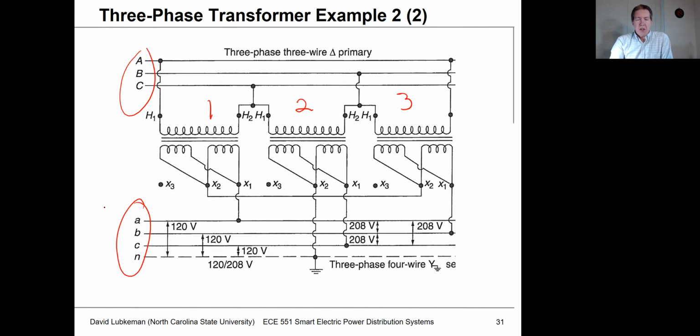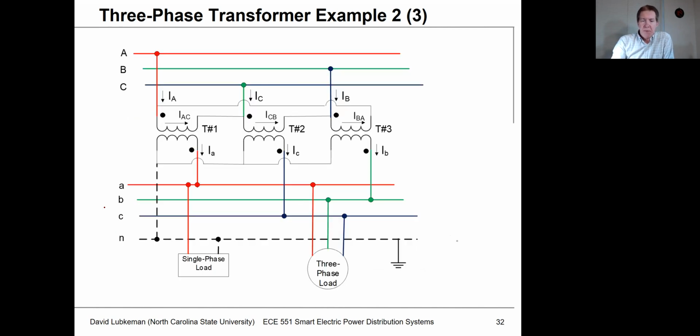So in this particular case, the way we're going to do this is just simply draw the loads into the circuit, and assuming we have rated voltages at the load side, work backwards. And I kind of redrew this to make this easier to see. And so basically note that these are the polarity connections, where we have H1 match up to X1 on the secondary side. This is how the connections would have to be set up. These show you the relative phase relationships.